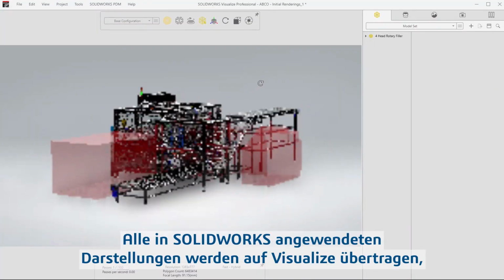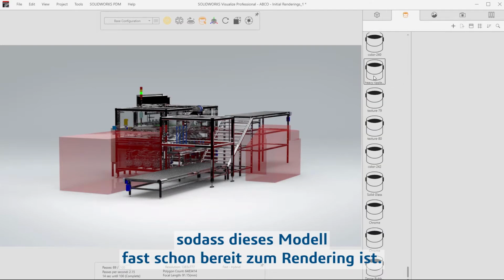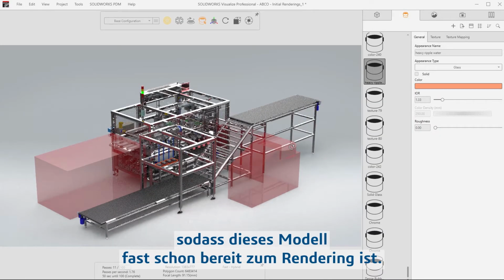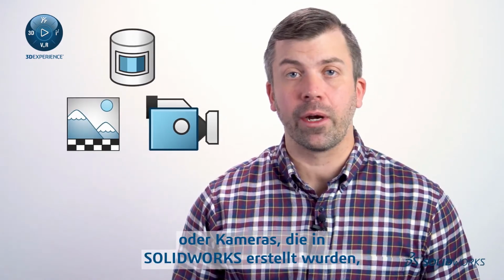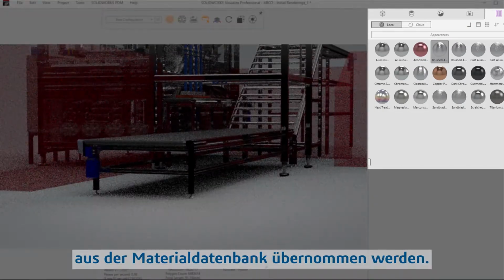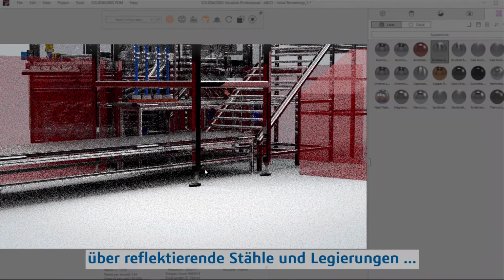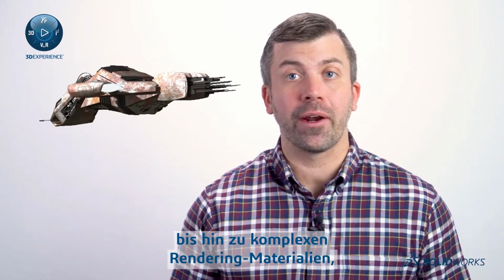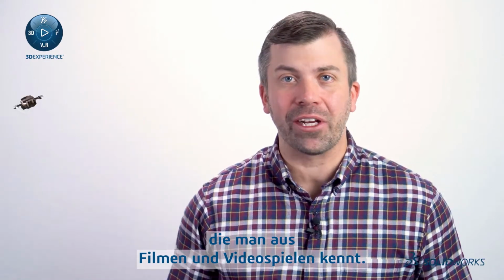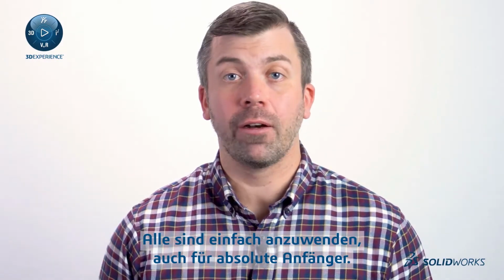All the appearances that were applied in SOLIDWORKS are carried over to Visualize. So this model is almost ready to be rendered. Things like decals, 3D environments, and even cameras created in SOLIDWORKS can all be repurposed. Applying additional materials is just a simple drag and drop from the materials database. I can use anything from basic colored materials, reflective steels and alloys, even complex rendering materials like those found in movies and video games. These are all easy to apply, even for the most novice of users.